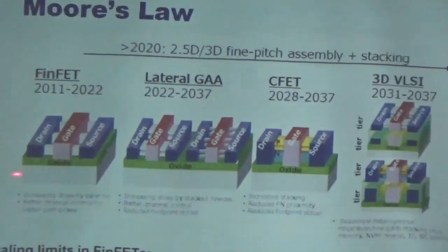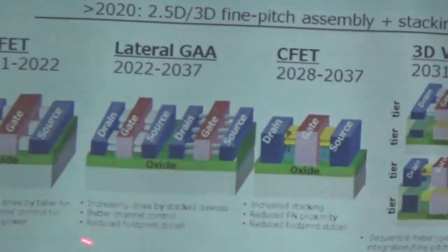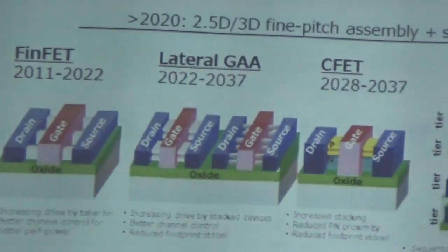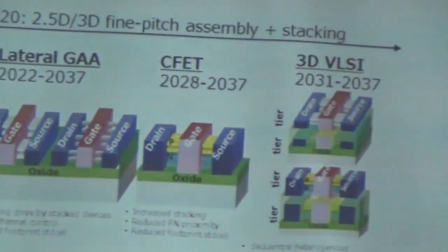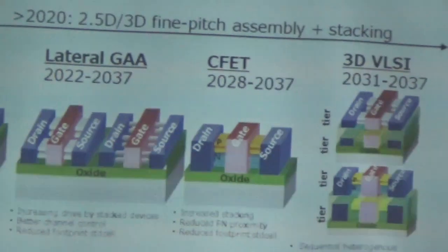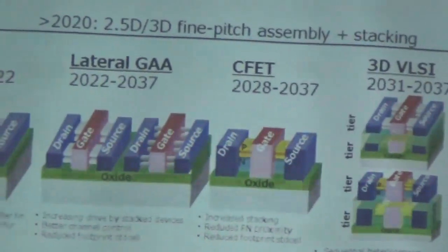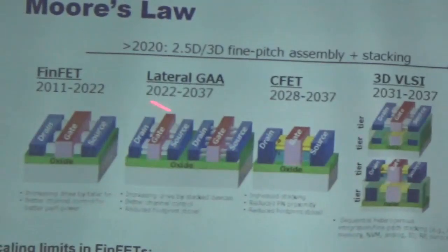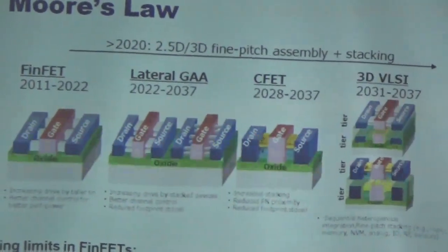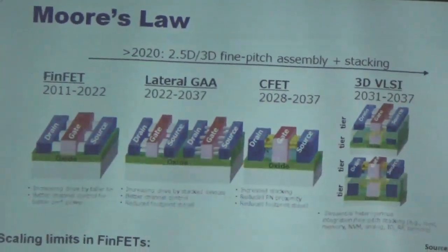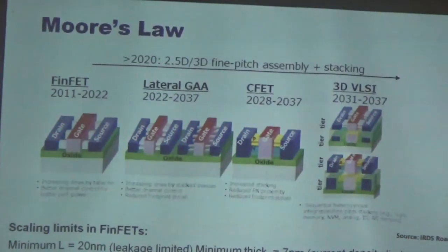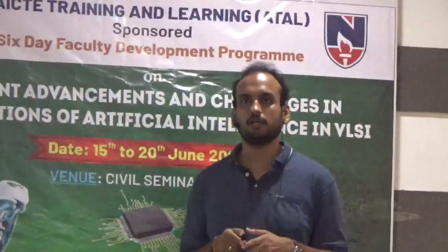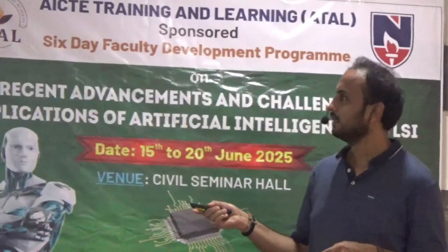They introduced one more dimension into this, which is the number of fins and the thickness of the fins. This is how they shrink the MOSFET transistor in one dimension and increase the size in other dimensions. So it's a 3D type of MOSFET, and it is widely used when you design at 3 nanometer, 5 nanometer. This is the device we are using, not the traditional planar MOSFETs.